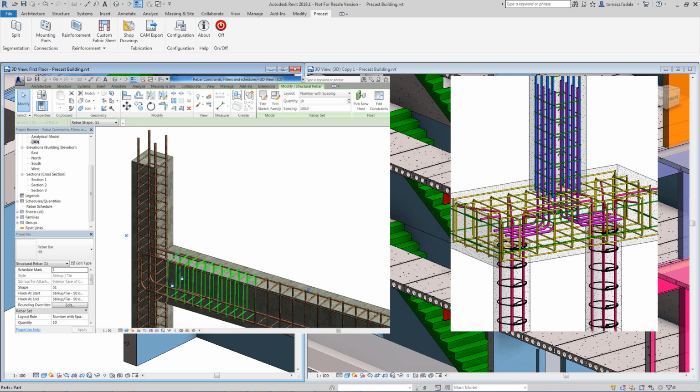So visually, without me having to look at some 2D annotation, which you would do in the 2D sense, I can visually identify, because I know that yellow is an N20 and red or pink is an N32. I can visually consume that information in a much different way, and I can look at that design and say, you know what, we might have some problems tying off the bars in that case. Maybe we should do ABC to change what we want to do.